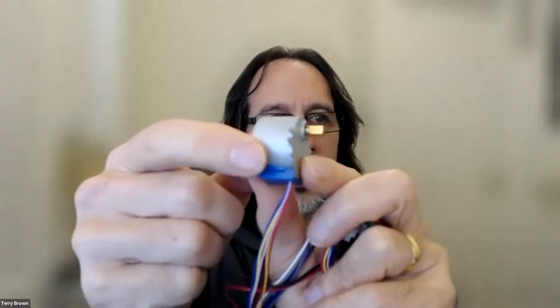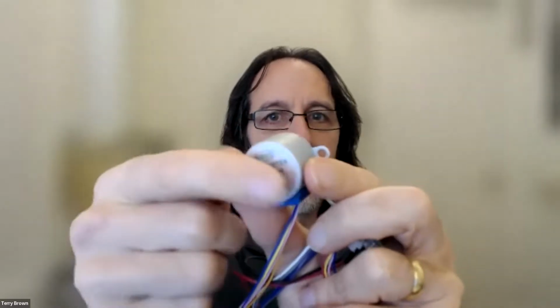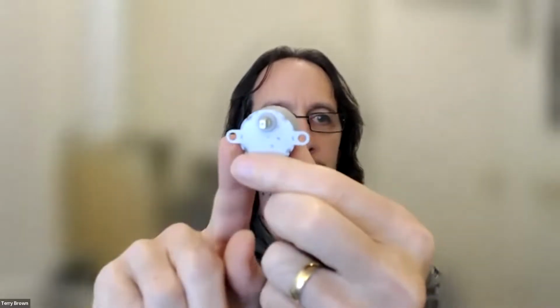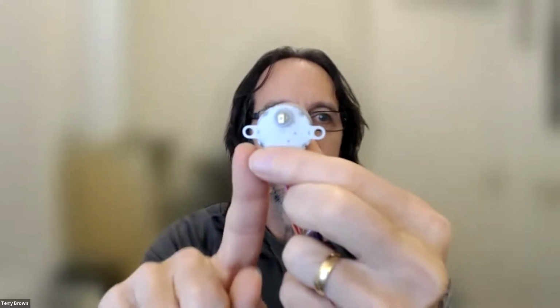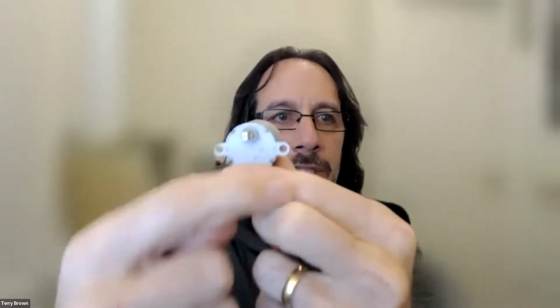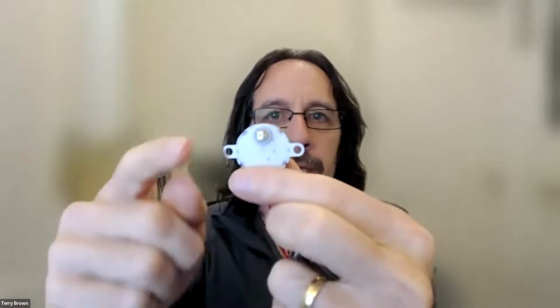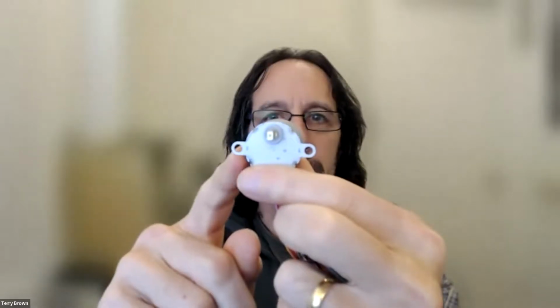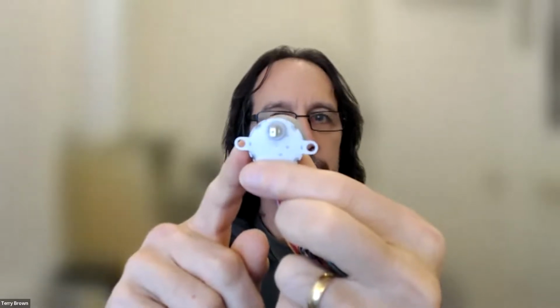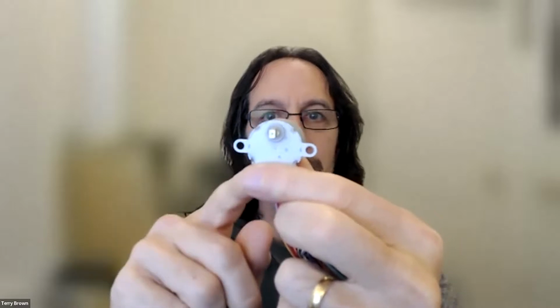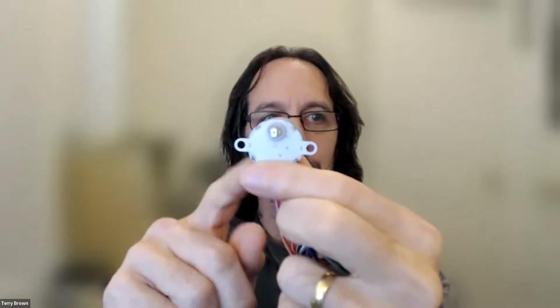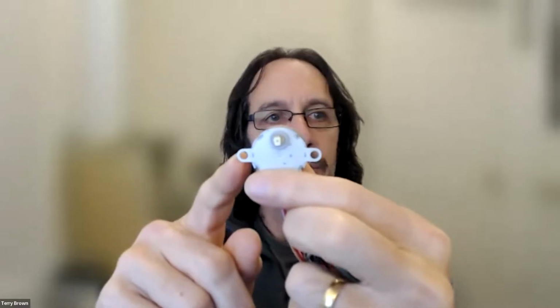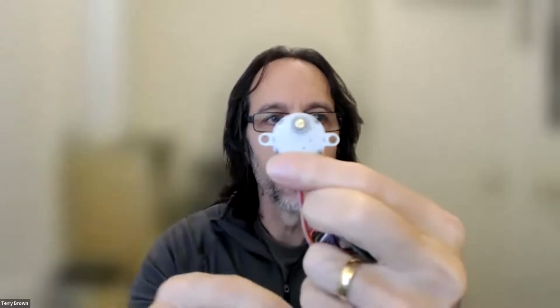So as a design exercise, you would need to know, same as we did in the problem that we've just looked at, we could work out a force up here and a force down here, and then calculate the stress that's developed in these little tabs here, and make sure that they can carry the load that's developed by putting a torque or a moment on the shaft.